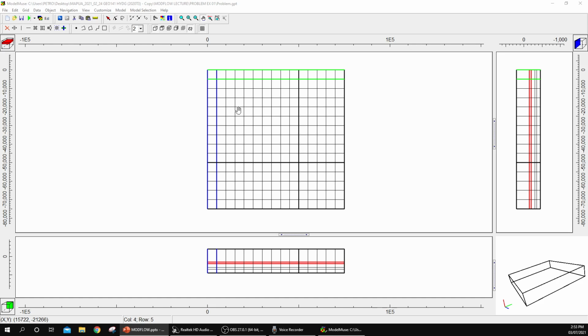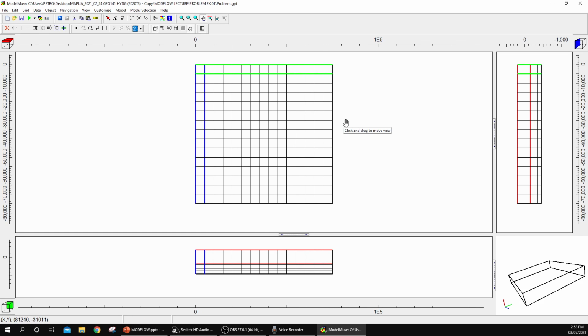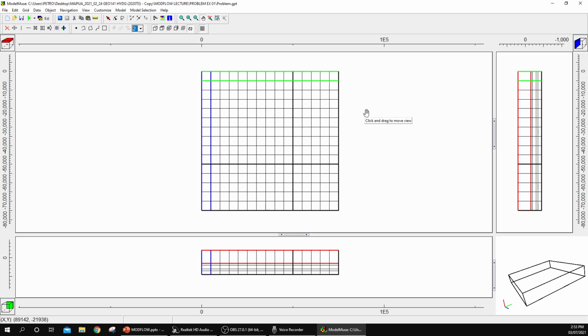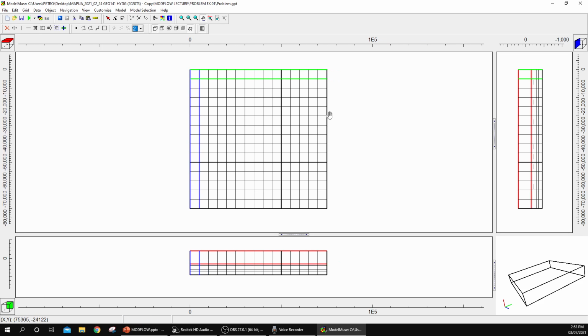Now let's move to drawing the lateral outflow boundary. Remember that this boundary is the outflow boundary, and this will only cover the upper aquifer and the middle aquifer. To start, we draw a line. You do this by clicking the Create Polyline object in the menu bar icons.